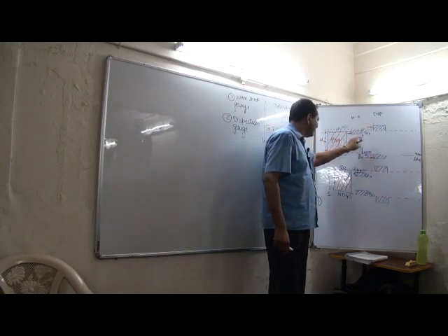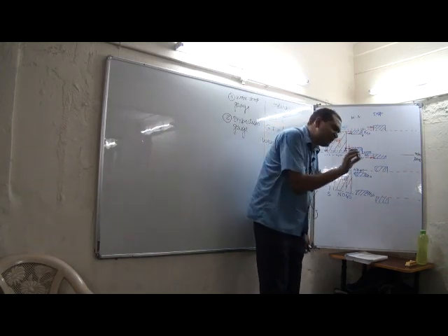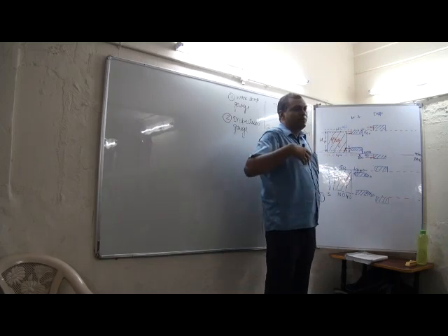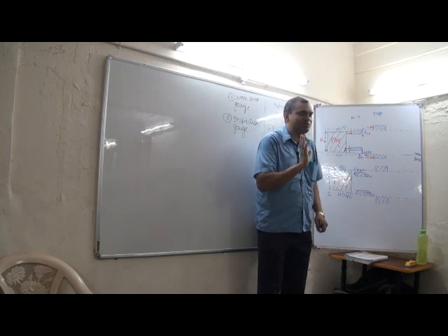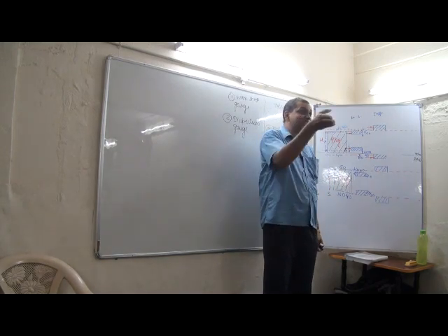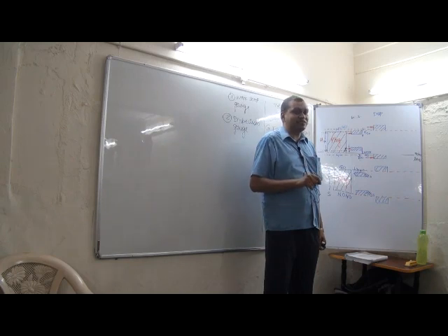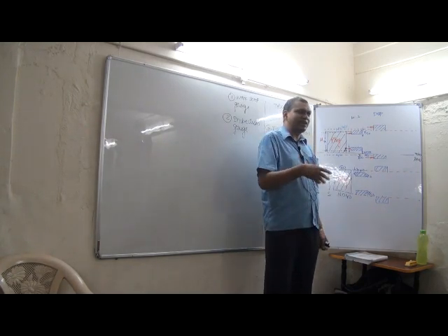Workshop gauges: some of the good parts will be treated as bad parts. For inspection gauges: some of the bad parts will be treated as good parts. Why? Because there is a tolerance on the gauges. That's why it is called a necessary evil. It's an evil because we are not able to filter properly.